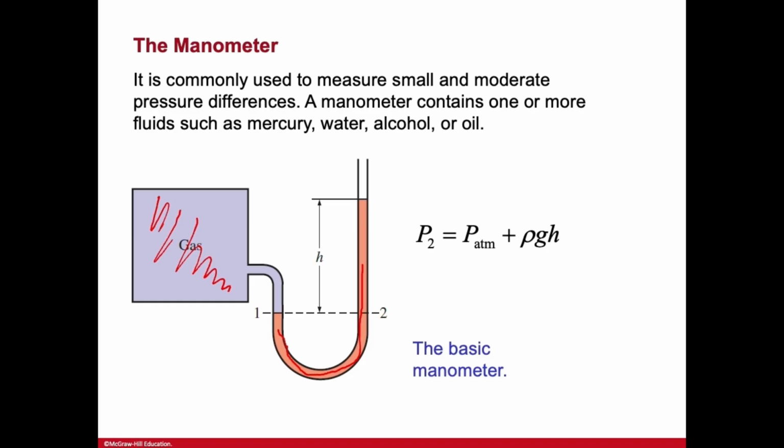So the way this goes about is you have this boundary or the edge of this liquid on this side of the tube. We know the pressure at P1 is equal to P2 from Pascal's law because it is at the same level. So we essentially extend the point 1 all the way to 2 so that it lies at the same level and is the same liquid. So the pressure at 1 and 2 has to be the same, right?